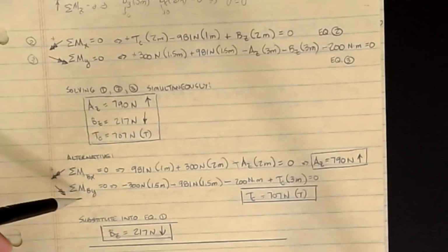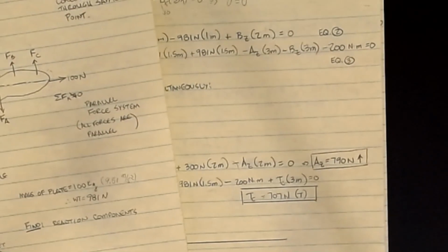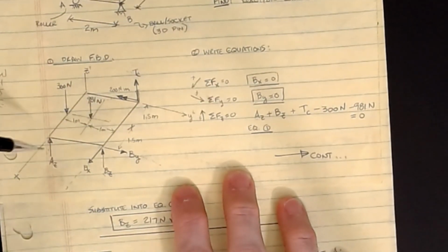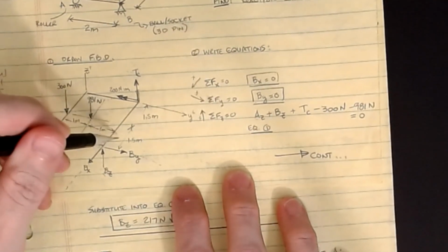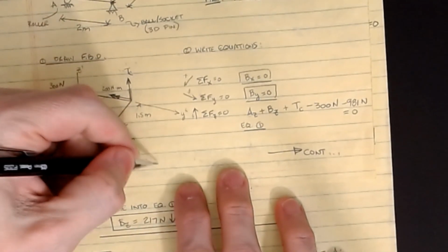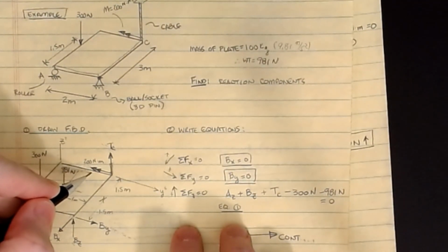I could get the tension by doing the moments about the y-axis through B. So my y-axis is here, and my y-axis through B would be acting there. AZ doesn't contribute. None of the B stuff contributes. I would get 300 times 1 negative, 300 times 1.5 negative, 981 times 1.5 negative, and TC times 3 positive, all about that axis. Again, we're looking for an axis that comes through here, and that would be the equation that I just wrote here. However, you do also get the applied moment, so don't forget it sitting here back in the back.